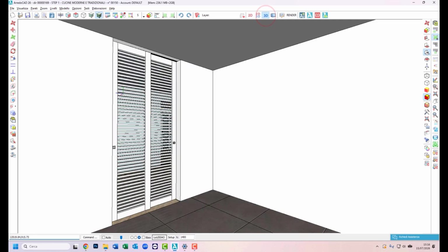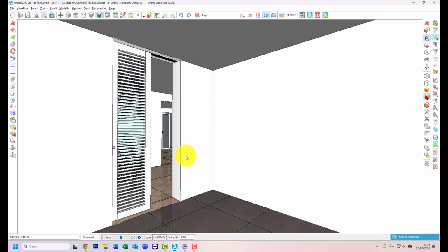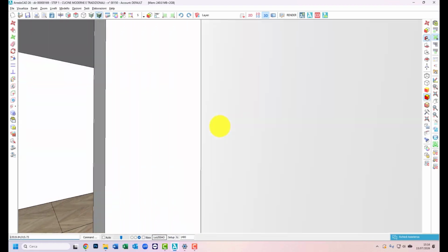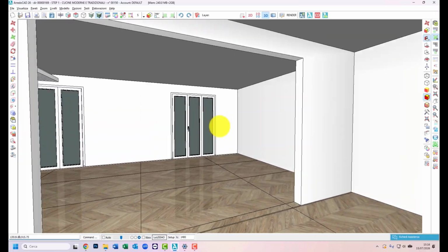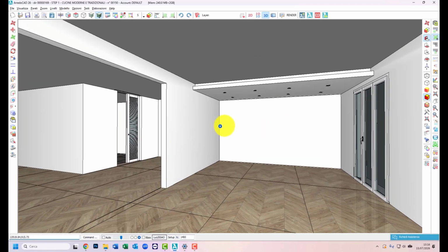Here I can also open the door. There's an automated tool. Click on the door, open doors, click OK, and set the opening. Again, right mouse click. The view unlocks. I use the mouse and the arrow keys together to move in any direction. With the mouse I rotate, with the arrows I move, right-click to lock the scene. I can also switch to a view without construction lines, which is a bit more refined.